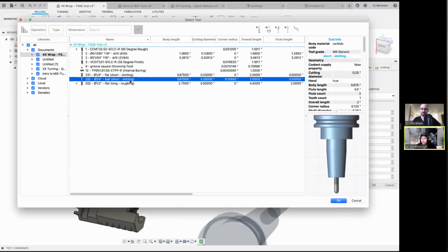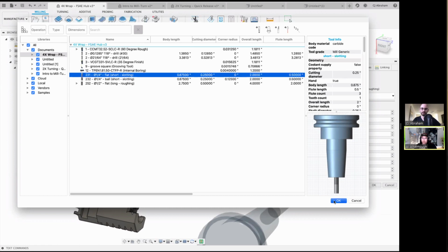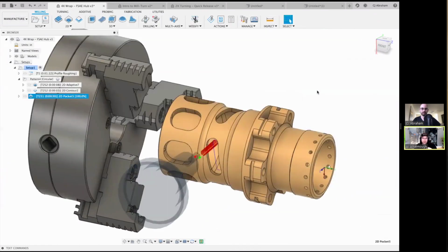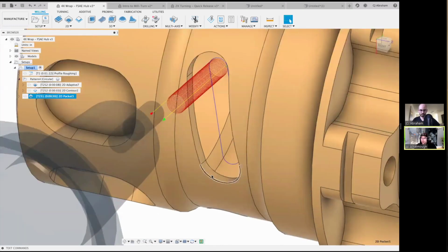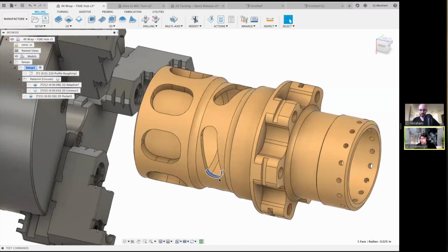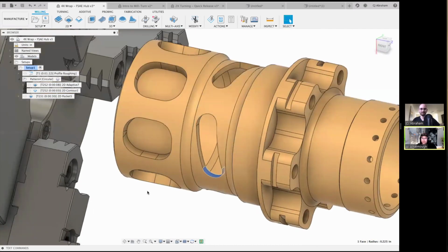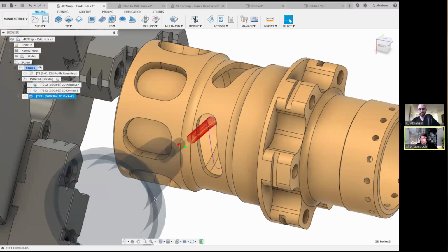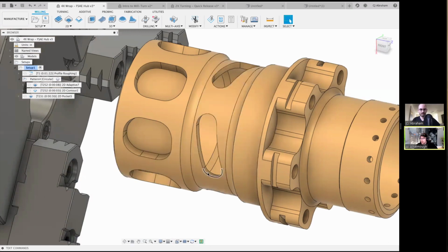While he's selecting the smaller tool, I think it is important to know about that minimum diameter. So when you're helixing in, there's a number that says what's the tightest helix that you can do. Just so you know, if you put in 10 thou, so that you just saw that helix that was just there, if you put in a super small number, we're still going to use the largest one possible. And we're just setting a range between the smallest and the largest possible helix diameter.